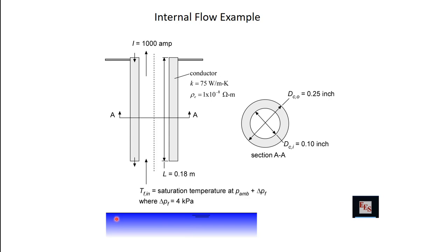And the vapor has to get out. And so what you do is you give it a limited number of paths to get out, and one of those paths is to travel through your current lead. So the vapor that's going through my current lead is coming from the boil off of the cryogen.